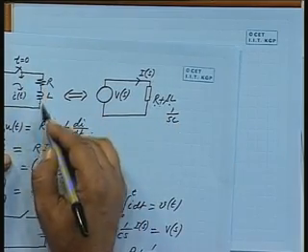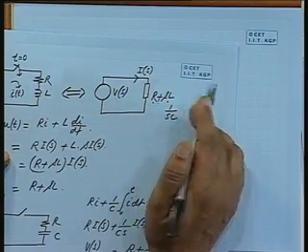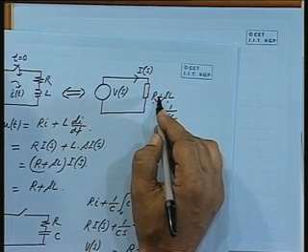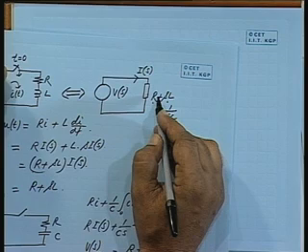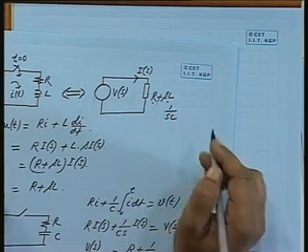So, if you have R, L, C, wherever there are resistances, you retain them as they are, inductance will be replaced by sL, capacitance will be replaced by 1 by sC, and in all network configurations henceforth we will be using the transform domain variables R, sL, 1 by sC. If we do this, then any network problem can be solved.